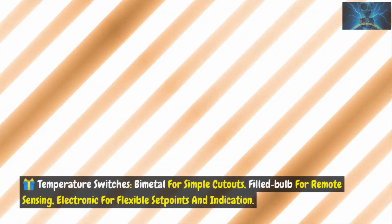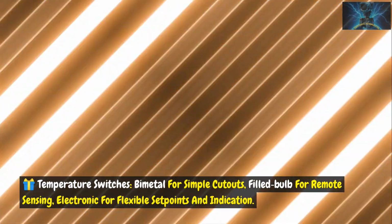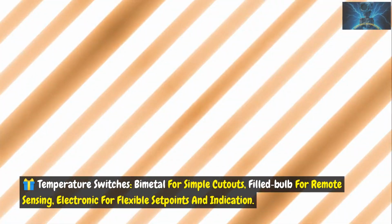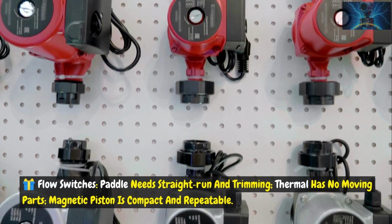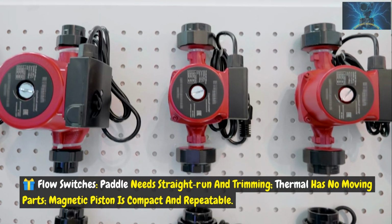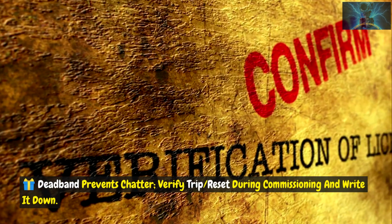Takeaways. Temperature switches: bimetal for simple cutouts, filled bulb for remote sensing, electronic for flexible set points and indication. Flow switches: paddle needs straight run and trimming, thermal has no moving parts, magnetic piston is compact and repeatable. Deadband prevents chatter. Verify trip or reset during commissioning and write it down.